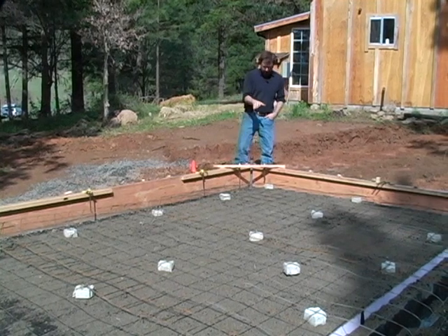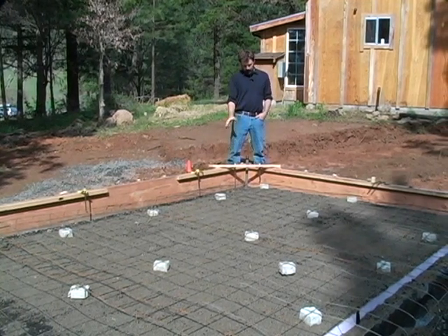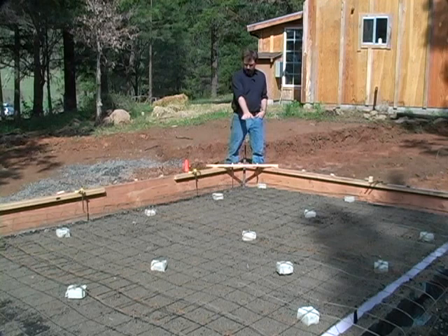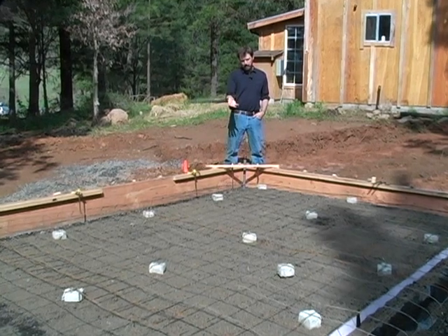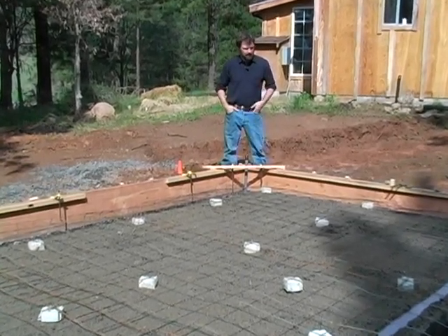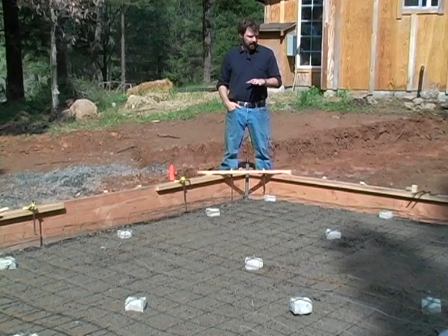Now, this is roughly what your subgrade will look like before you get ready to pour. We've got, again, our compacted gravel, the gravel bed raised up, the visqueen, which is the waterproof plastic, the foam insulation, the sand, the dobies holding the steel up off of the sand. So this is basically a complete ready to go slab.